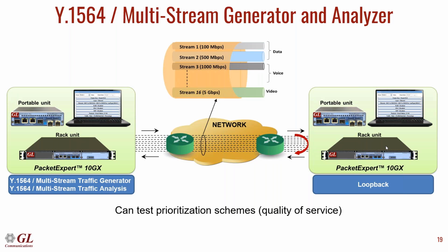Yeah, I'll answer that. Yeah, that's true. The loopback side is not just a physical loopback. It does swap the addresses, but there's no measurement done on the loopback side, and everything is done on the generator side. So both generator and analyzer are running on one side. So all the measurements which we produce here are actually round trip measurements. So even the delay would be round trip delay.